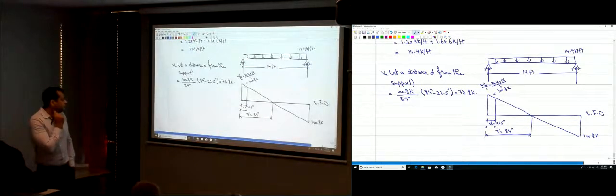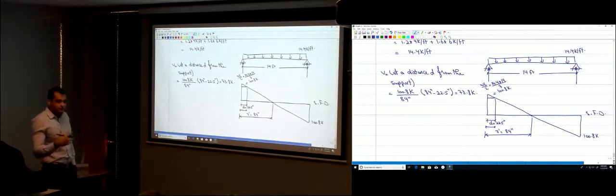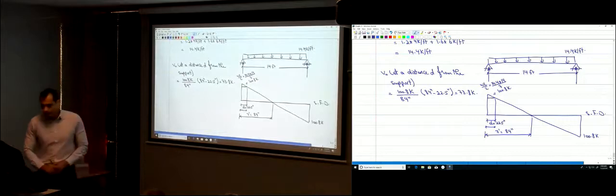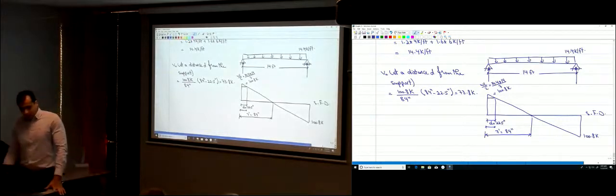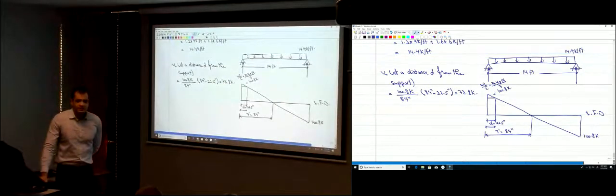So that's the value that I should design my beam for, okay? Not 100, it's just 73. So if you design it for 100, your design is going to be more safe. You're designing for 100 while you can actually design it for 73. That's more than 20, like 25% decrease in the value of the shear. So now we have the ultimate that I should design my beam for. What are the steps now?